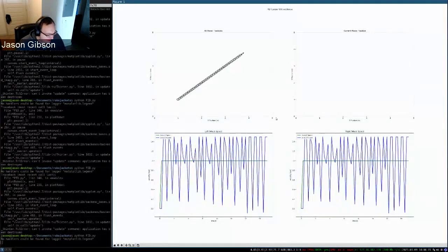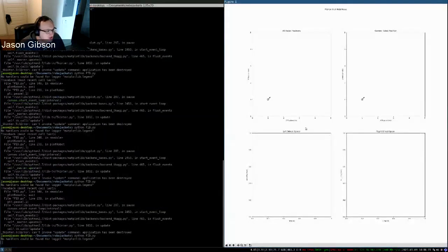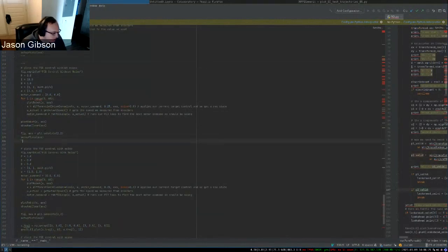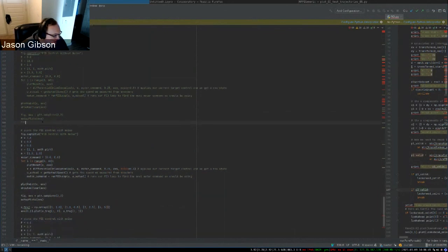Again, just to reiterate as we go into the next section, how you tune PID is you set the P value until you reach your set point as quick as you would want. Then you increase your D until you don't oscillate as much, to a reasonable amount, and then you increase your I to handle any steady state error that you might have.